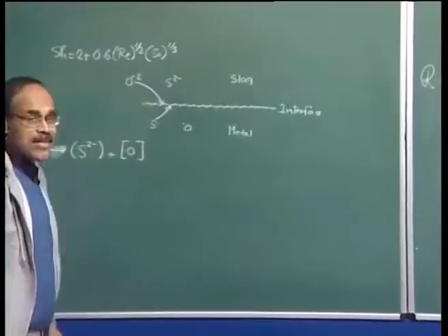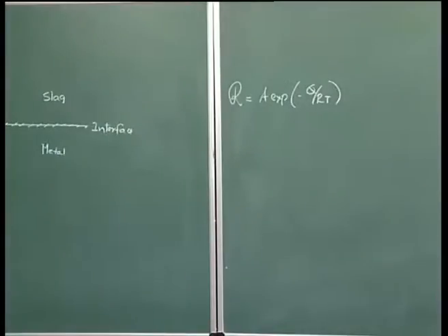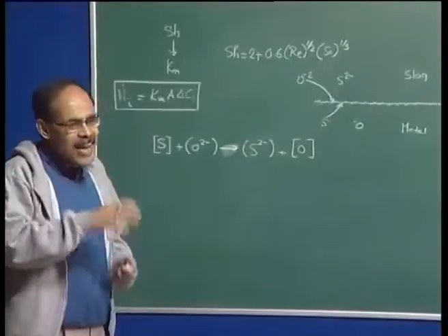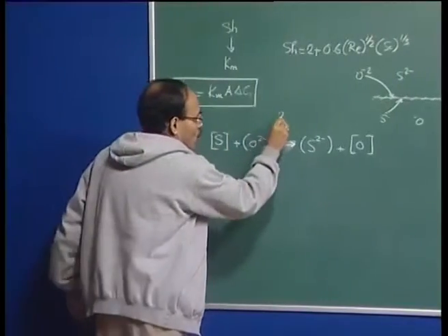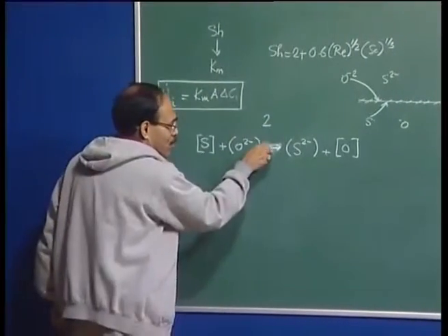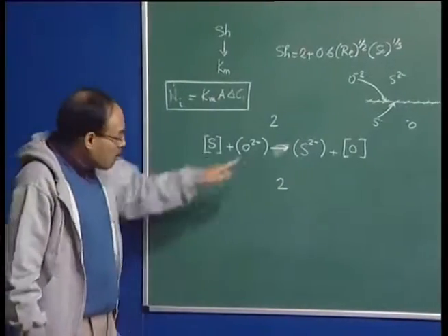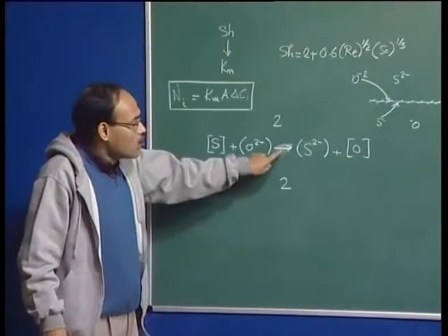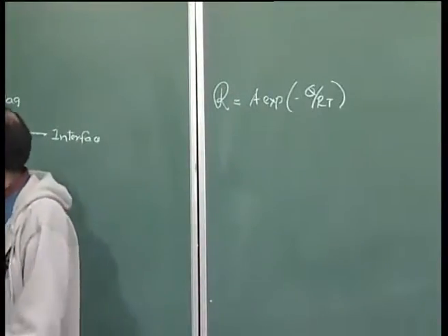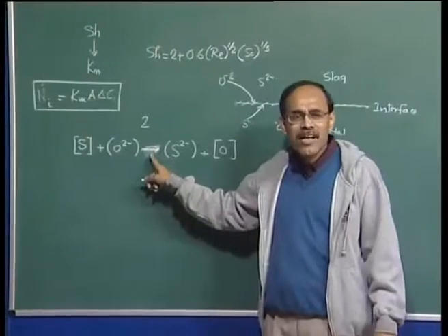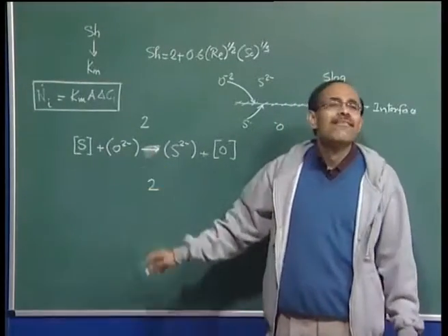Therefore, this tells us that as temperature is increased, the rate of the chemical reaction increases significantly. So the rate of a chemical reaction, okay, we have two mass transport steps before this chemical reaction and two mass transport steps after this chemical reaction, and now we are looking at just this one step. We conclude that, based on the Arrhenius rate law, we can expect that the rate of the chemical reaction under steelmaking conditions, where temperature is 1873 Kelvin, could be very, very fast.